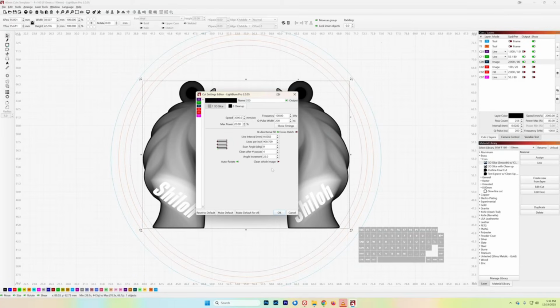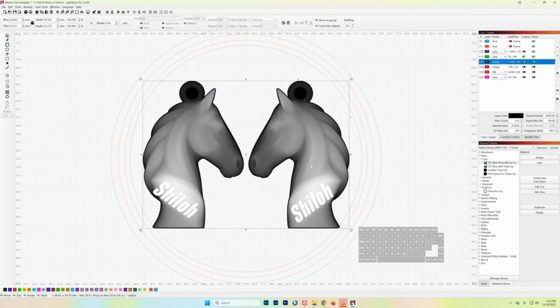So when the fiber laser stops engraving a point, like in this case, one of the first things that you see it engrave is going to be this S, or in the case of the one that I actually videoed, it's going to be the other one that we used in Blender. So it's the river. So you'll start to see that text appear first. When the laser stops carving out these letters, because they're at the top, the cleanup pass won't hit them either. So it's not continuing to etch or engrave these away. So it's going to give you a little bit crisper results. So those are the settings there. And at this point, we are basically ready to send this to the laser.